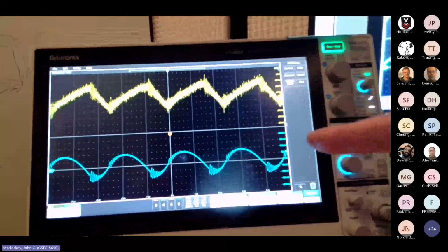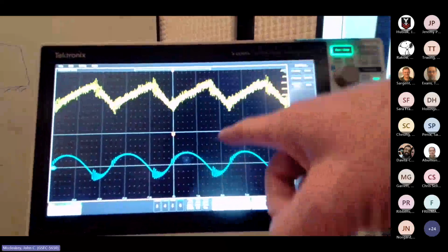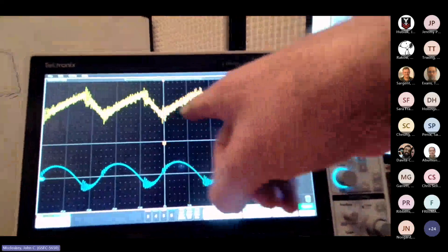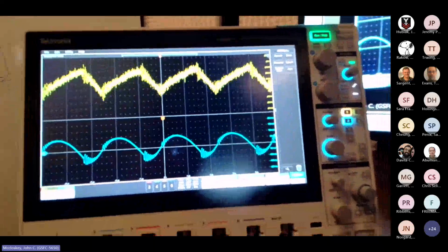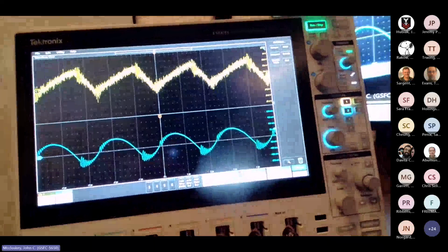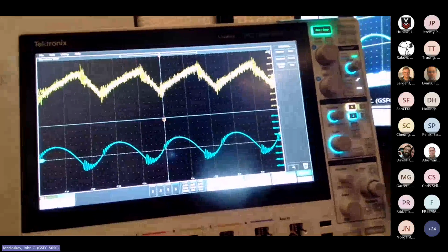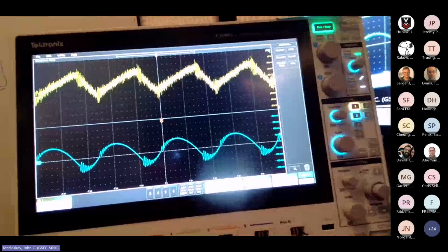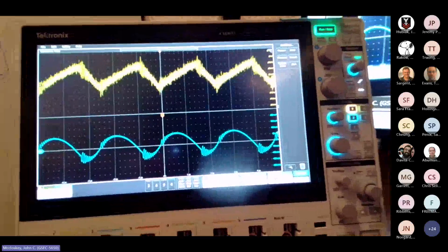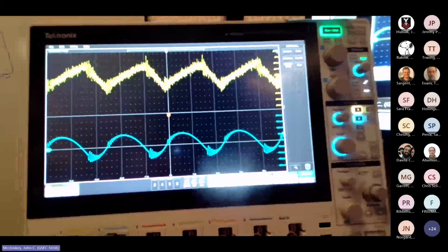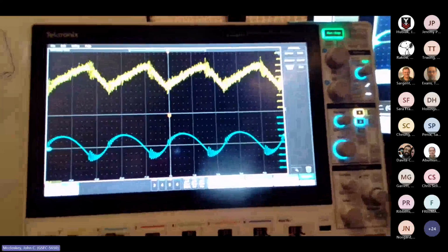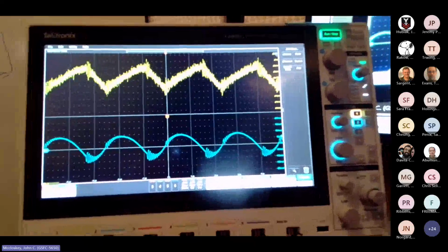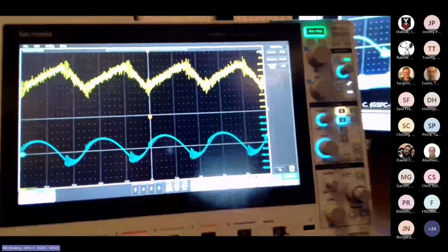And I guess another significant thing is the period. That's about 2.5 microseconds. It's 1 microsecond per division, so from there to there, 2.5 divisions, give or take, so about 2.5 microseconds. So it's right around a 400 kilohertz switching rate, which is right in line with what the spec sheet says. It's 400 kilohertz plus or minus, I don't know, 10 or 20% or something. But we're sitting right around 400 kilohertz. So we would expect, for a periodic signal, it's ugly, but it's periodic with a fundamental of about 400 kilohertz, we should expect to see a harmonic train with a fundamental of 400 kilohertz, and then harmonics of that.